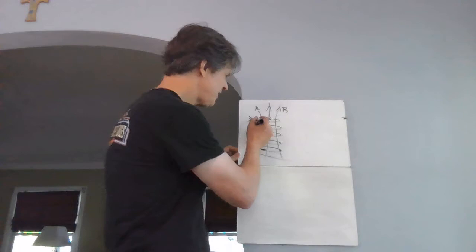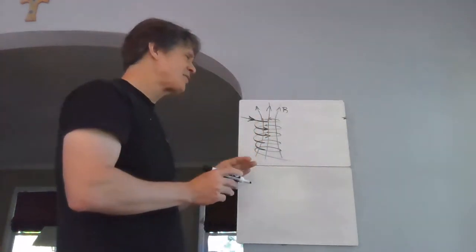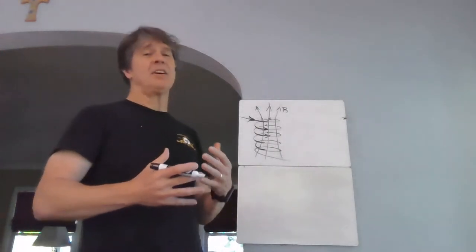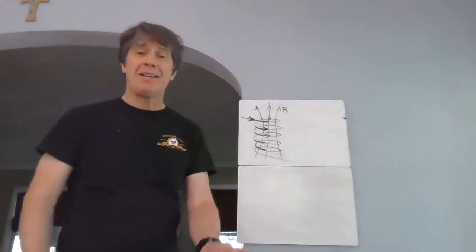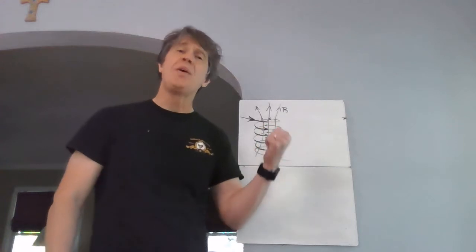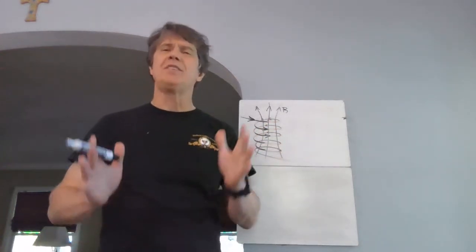So an increasing current in this direction is going to automatically cause the inductor to get all upset and try to make a current that flows the other way. It might not win. It might not really make a current flow the other way, but it'll have the effect of slowing this one down, or at least reducing its rate of increase.